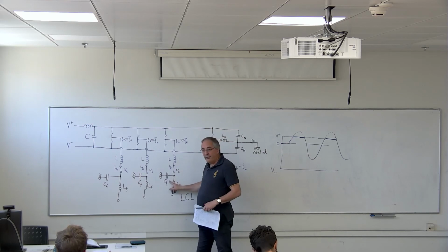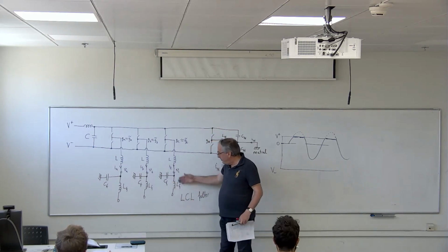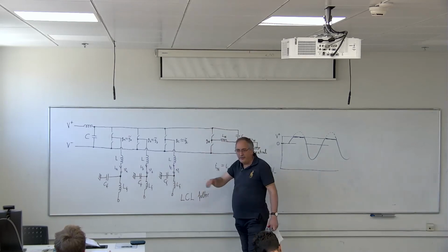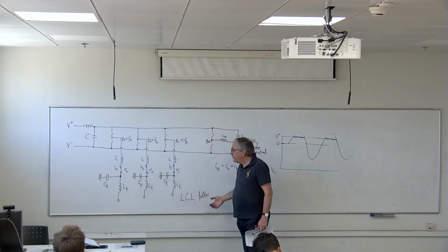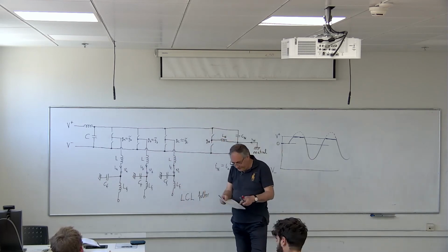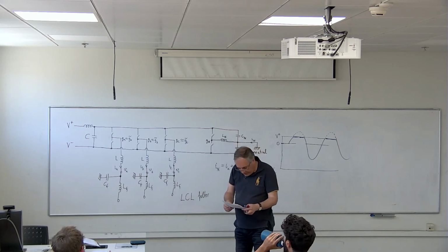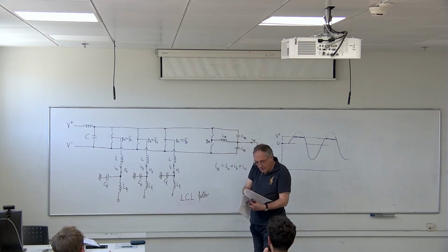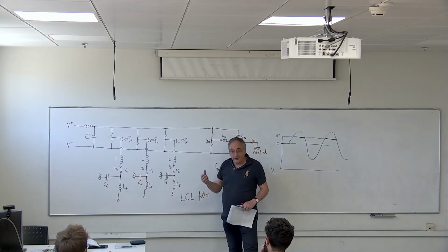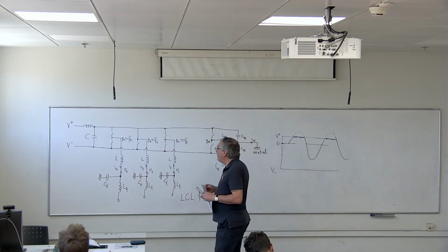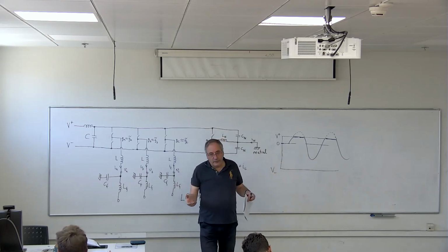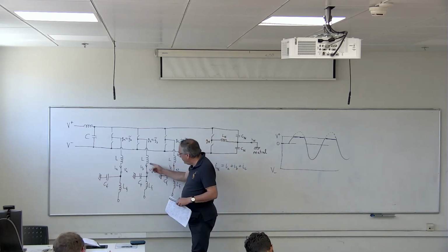In most inverters, you have the capacitor, and in good quality inverters, you have LCL, and you have even more circuits, which I will not describe now, which prevent common mode voltages from propagating from the inverter to the outside world. We don't discuss it. Okay, now, I'm nearing the end. We usually distinguish between voltage mode inverters, where the control algorithm controls the output voltage G, and current mode inverters, where the control algorithm controls the output current.